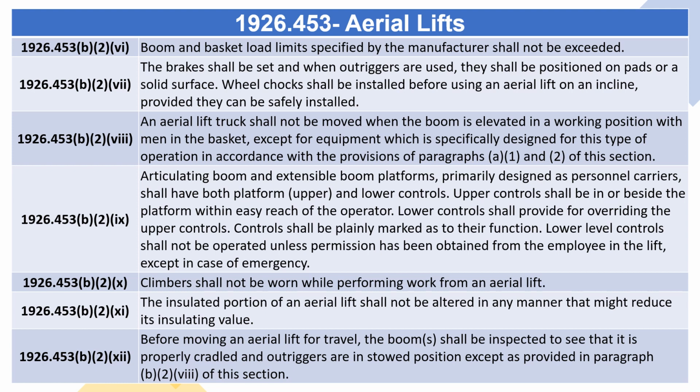Lower level controls shall not be operated unless permission has been obtained from the employee in the lift, except in case of emergency. Climbers shall not be worn while performing work from an aerial lift. The insulated portion of an aerial lift shall not be altered in any manner that might reduce its insulating value. Before moving an aerial lift for travel, the boom shall be inspected to see that it is properly cradled and outriggers are in stowed position, except as provided in paragraph (b)(2)(viii) of this section.